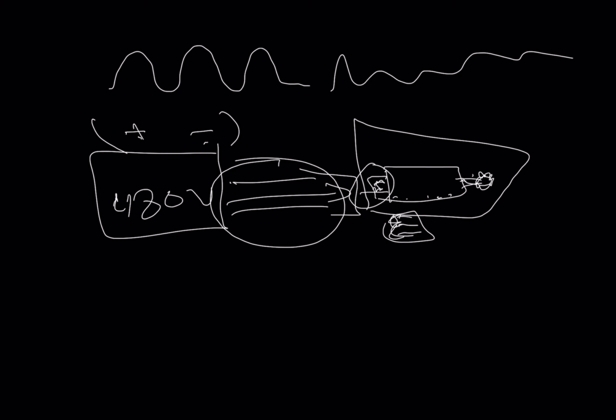For the ground, we check every line to the ground to see if somewhere the insulation from the lines is being burned out and is making contact with the ground. The ground can be the conduit coming from the main panel, or a raceway, anything. You have to check it all the way there.